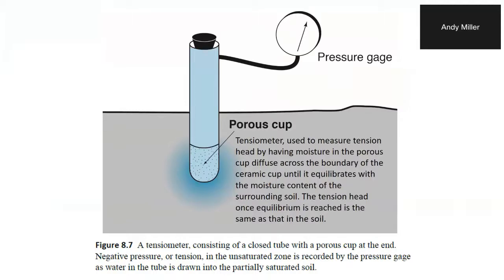So you'll remember that we have talked at length about hydraulic head. We've talked about the component of head that's a pressure head, that's positive pressure beneath the water table. And then we introduced this concept of, in the unsaturated zone, the sort of inverse, where we have negative head. We have tension head, water that's being held in pores by surface tension. And so I'm just going to, even though I showed this last time, start here and then move forward.